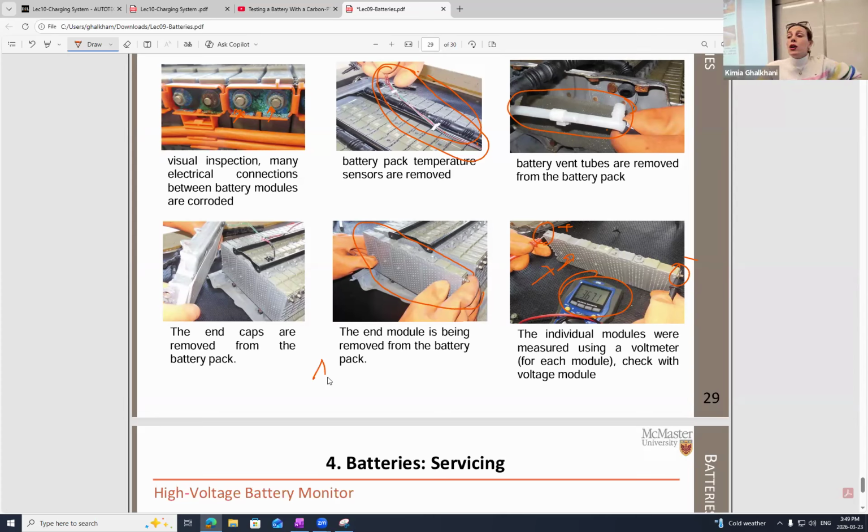And then I'm seeing that my pack's supposed to give me 48 volts. Everything fully functional. I was getting 48 before holiday. And when I'm back, I see my pack is providing only 30, right? Means I'm having some leakage. Some of the cells are bad. And I was using prismatic. That's what I said. Next time I'm going to show you what I had.